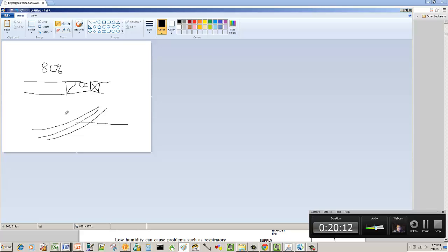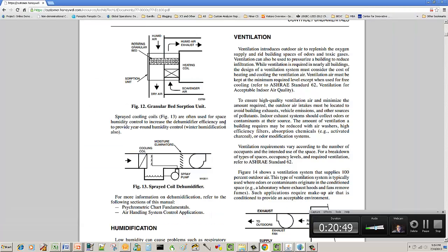which means that as the air cools down, the molecules slow down, there's less room in the air to hold the water, and the water is essentially going to fall out into the condensate drain, because we call water that's falling off of a coil condensate because it's condensing. The water in the air is condensing, so it's condensate, and it runs down the drain, and humidity leaves the air. We warm the air back up, and lo and behold, we're at a lower humidity point. This will make complete sense when we move through the psych chart, but you're just going to have to trust me on it right now.